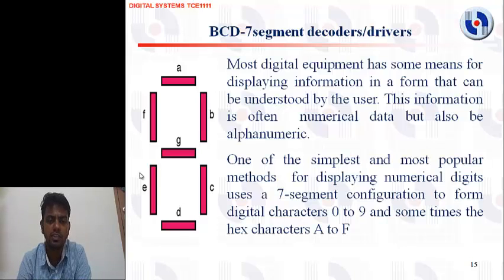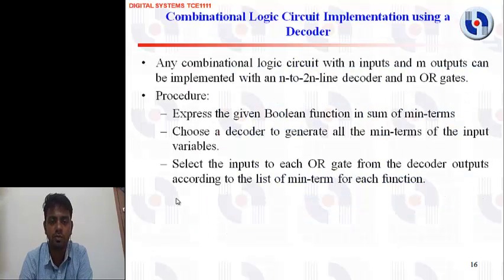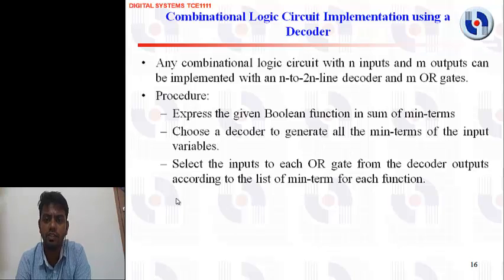For many instrumentation industries, or for development of instruments, we can use these 7-segment decoders as a part of the instrumentation. Any combinational logic circuit with n inputs and m outputs can be implemented with an n to 2^n line decoder